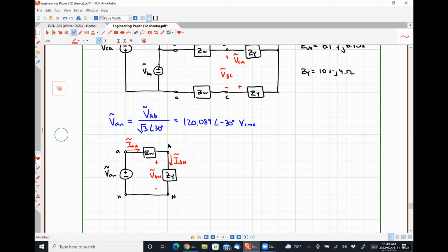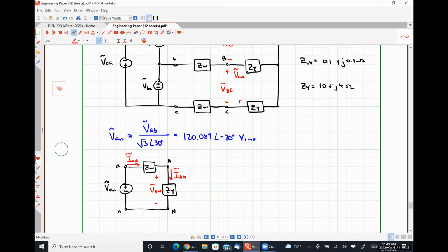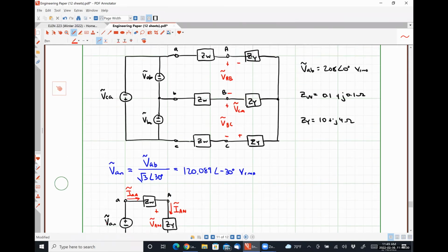No. Okay. But I would argue that if we can figure out the phase voltages in our load, like this guy right here, VAN and VBN, it should be rather trivial for us to determine the line voltage VAB. It's going to wind up being literally the exact same transformation that we developed for the sources.